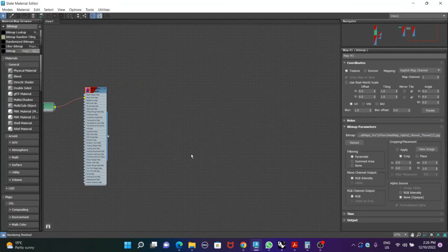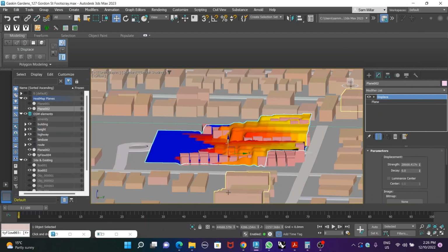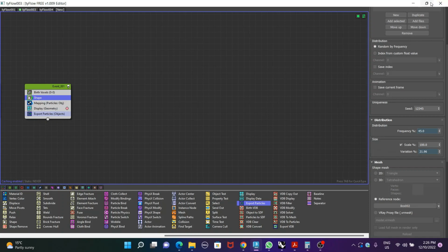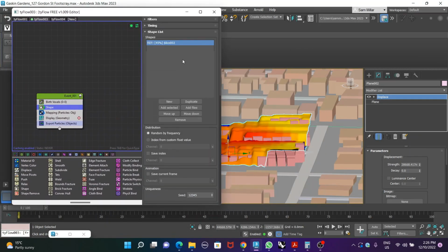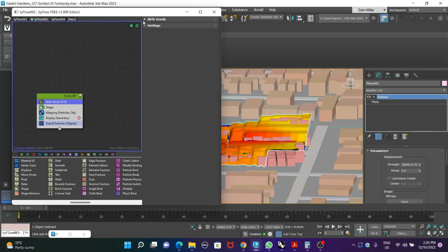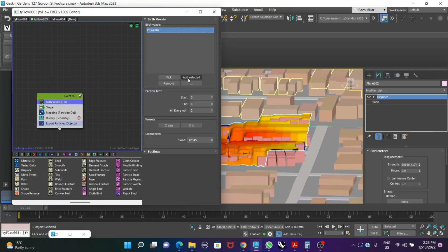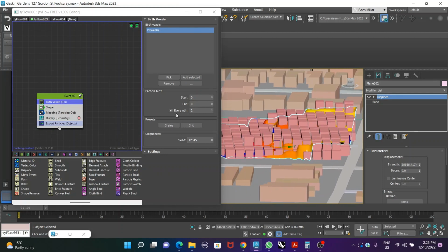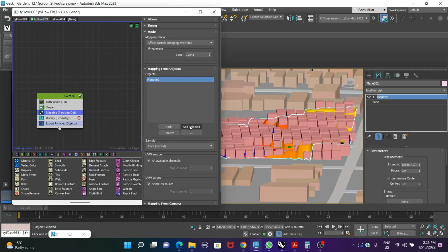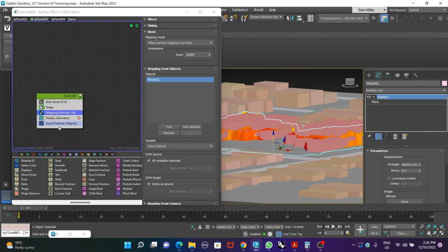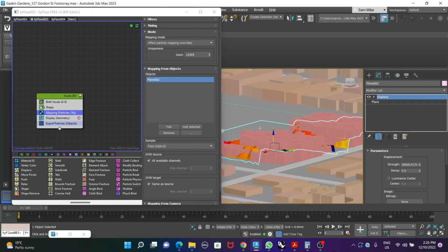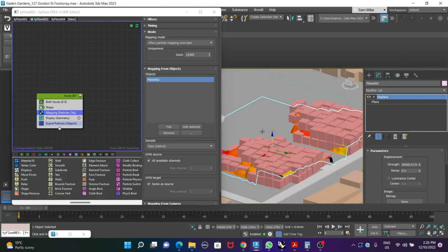Now the nice thing here is that we can continue to adjust that height, but what we then need to do is come back into our TyFlow Voxel editor, and we just need to re-link those planes because it doesn't automatically update them. And we can see how that adjusts. And it's the same here as well. So then we might bring that down again. So that's got some nice variability there.